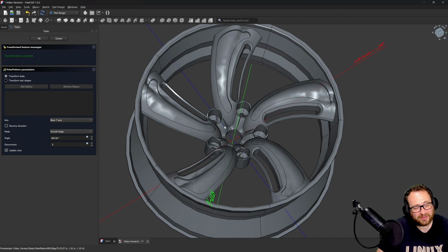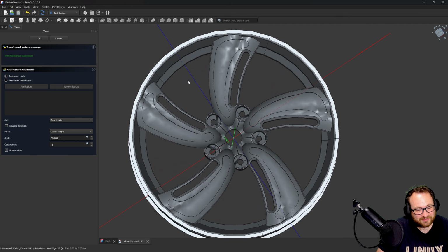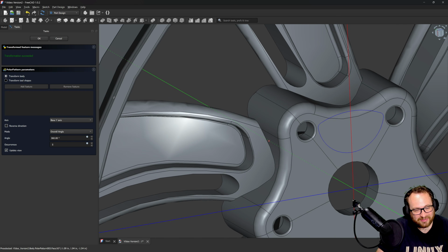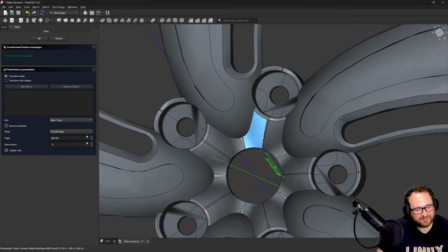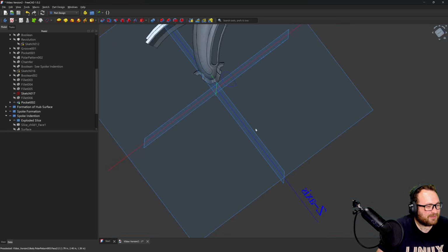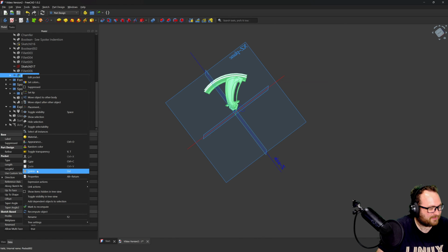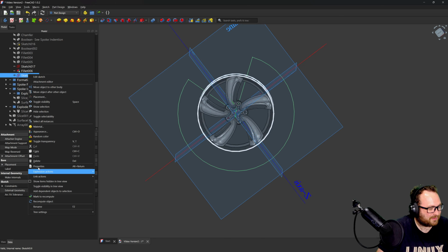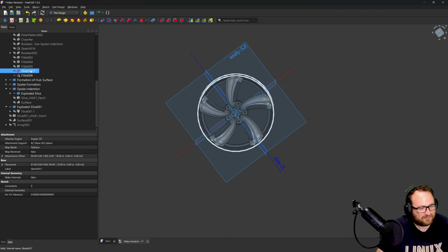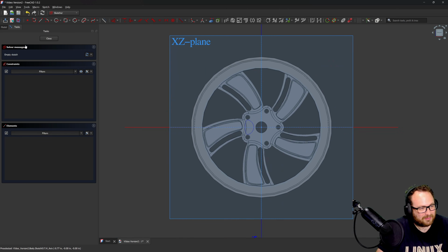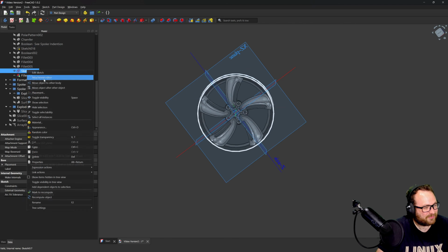So in the future, if you have a hard time with one part of a body, doing a body pattern, if there's symmetric pieces like this, might be a cool strategy. If we didn't have just that one thing, it looks like everything else would be perfect. So I'm going to give it up there. I'll probably delete my pocket. I can get rid of that sketch. What is the sketch 17? I think I've got a blank sketch, so I'll just get rid of that too.